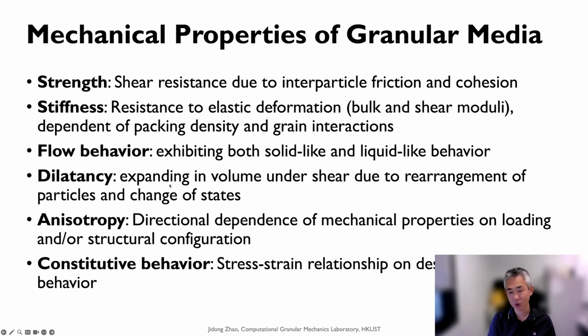This is quite a unique property of granular matter. It is indeed a very core concept in soil mechanics, and different people have developed constitutive models around it. So the dilatancy law, or dilatancy relationship, is the core of many constitutive models in soil mechanics.